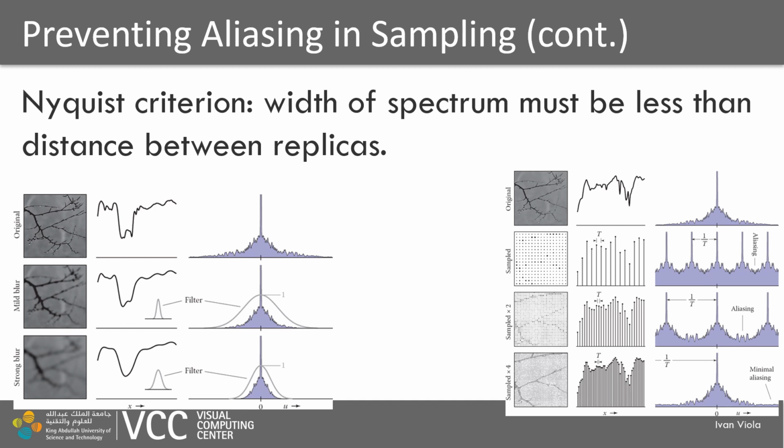We are coming back to the beginning, where we stated that we need a certain Nyquist frequency corresponding to a certain sampling rate. So our function, which we are sampling, cannot exceed a certain presence of frequencies, and it should have only a certain interval of frequencies. But sometimes we cannot influence the sampling rate because our camera sensor has just a certain resolution and we cannot increase it. Therefore, it is important that we are band limiting the input signal.